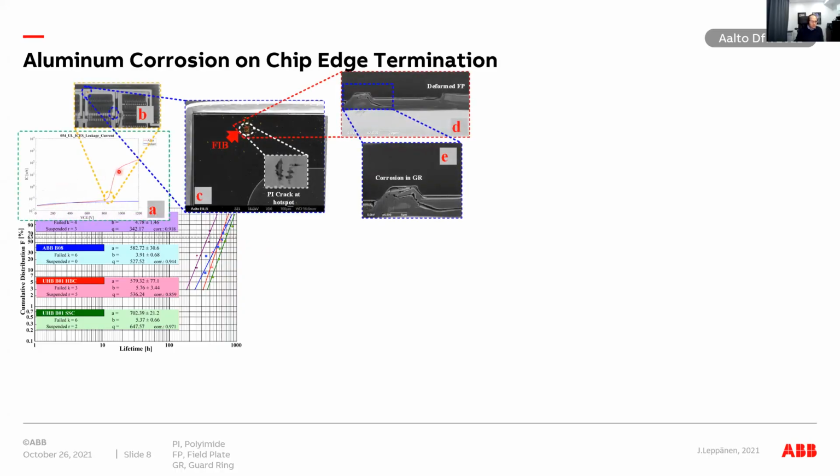But okay, what we saw there. First of all, we realized that again the leakage characteristics had deteriorated dramatically. Then we used this information and did lock-in thermography and found out that there is a hotspot in 2 of the corners of one of the chips. And then we made a SEM image and overlaid this lit image on top of it.